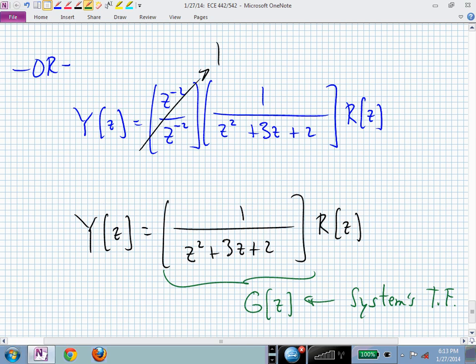Maybe you created this g of z to actually be a low-pass filter. And now you want to implement that, and somebody says, oh, here's your transfer function. Have fun. So you go, that's fine. I can create a difference equation that I can then just code into my microcontroller or my computer, that if you give me a string of values coming in that you want filtered, I can number crunch and give you the output that's a filtered version of whatever you started with, based on this system or this filter, whatever this transfer function represents.